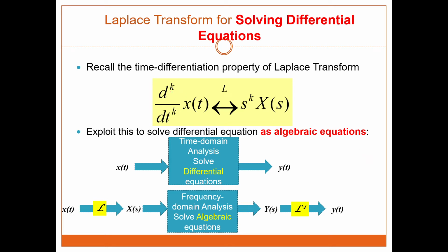Okay, basically if you have the differentiation of a function x(t) in time domain, you can convert it to Laplace transform by just changing the function to X(s) multiplied by s. If it's a first degree, you just convert once only, but if it's a second or third degree, you have to change this to s squared, for example, and then there is an s X(s) and so on, plus the initial conditions.